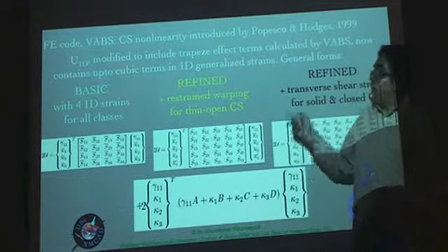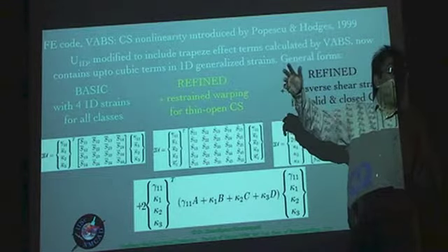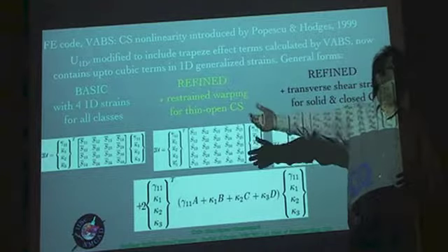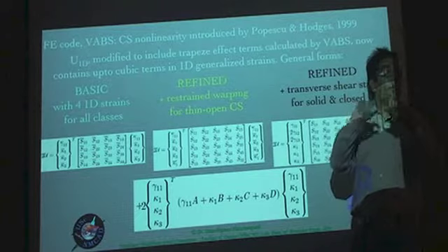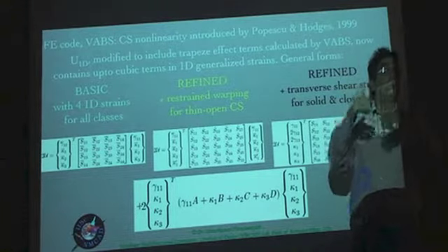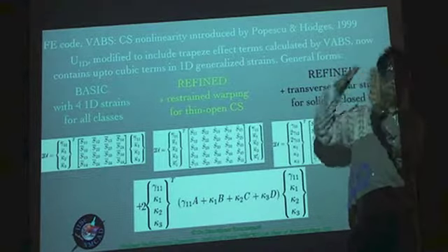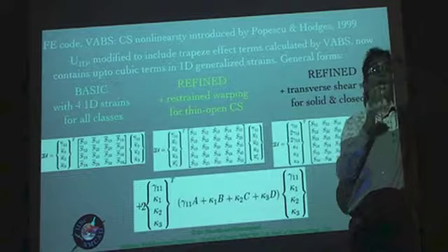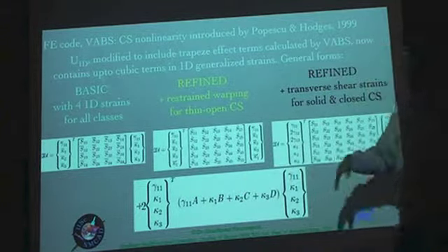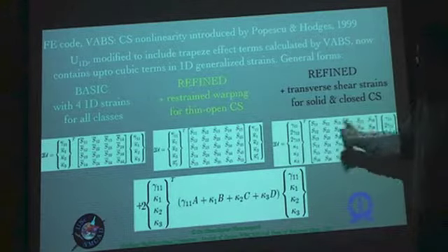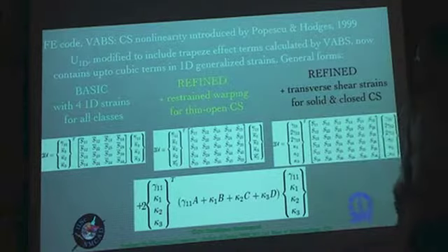Whereas you saw in the previous slide, we can go up to even quartic terms with a closed form analytical solution if the geometries are simple. By simple we mean basically it can be thought of as composed of strip-like geometries. So basically either a single strip or multiple strips to make either a T section or I section, L section, channel section, hat section, whatever. So basically our star section, cruciform, etc. In all such situations you can get closed form analytical solution even up to the quartic term.